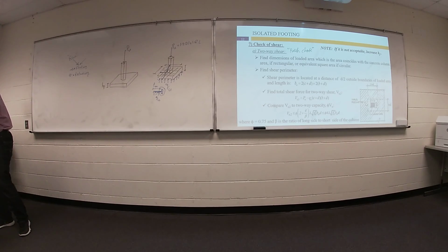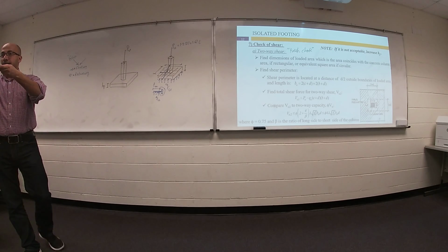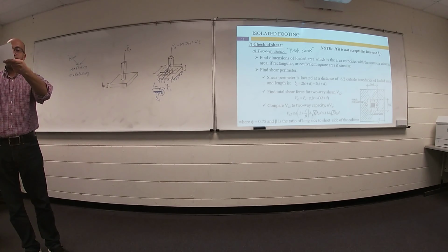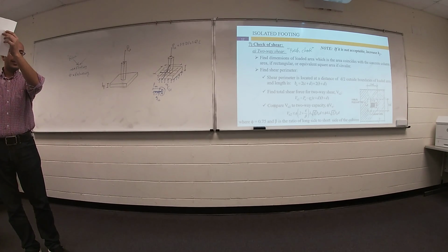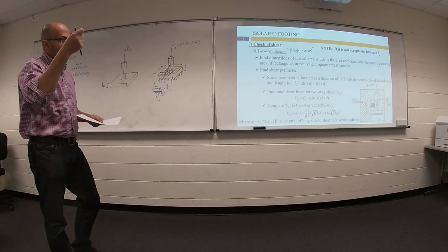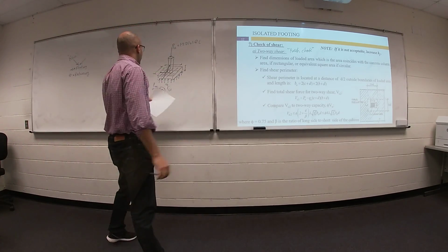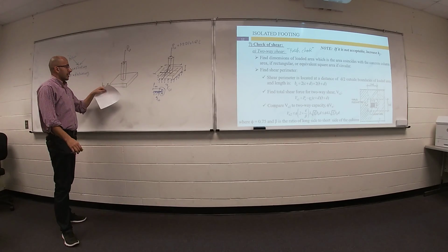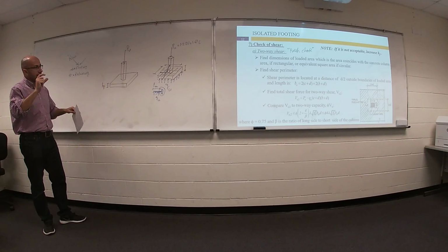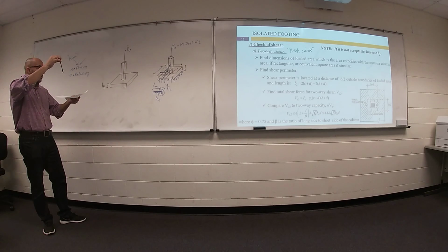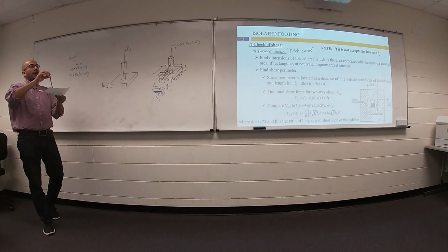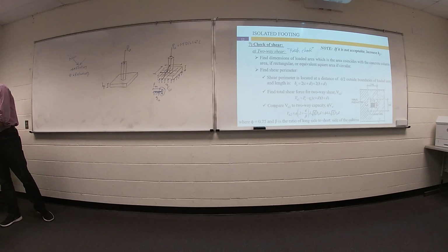I'm worrying about this phenomenon. Can you see what happened? This is called punch. Your column may be thin, carrying too much load, or your footing is too thin in thickness. So maybe you can expect punch in this area, so we need to check.